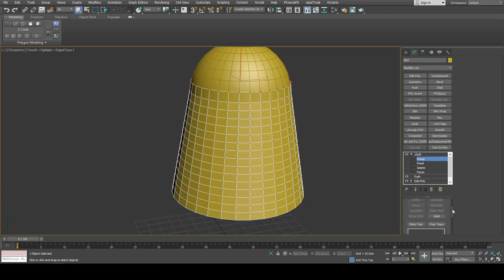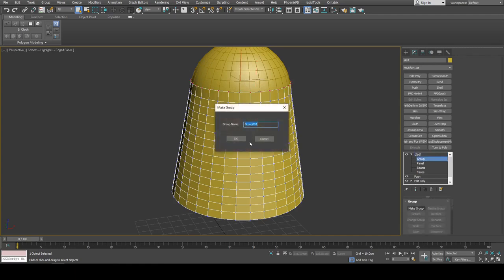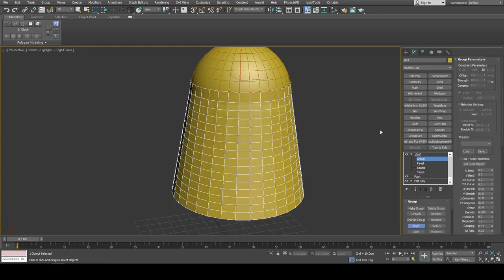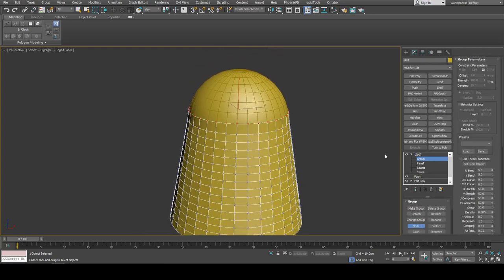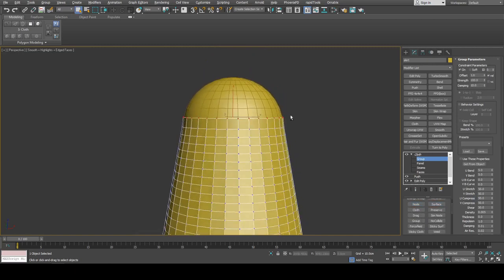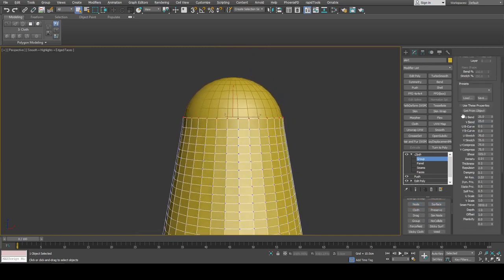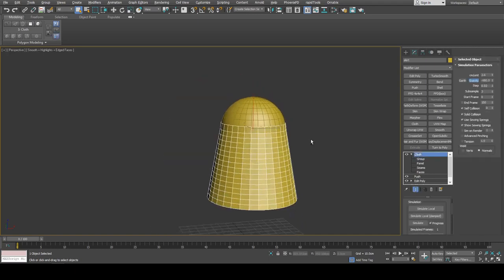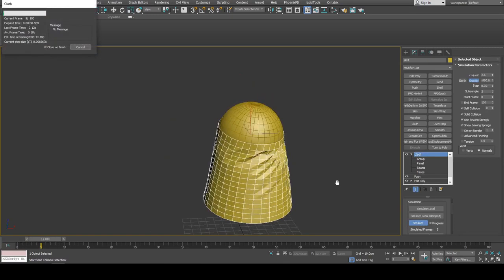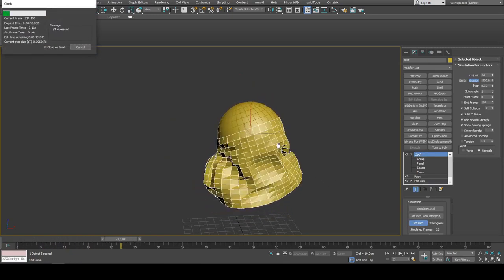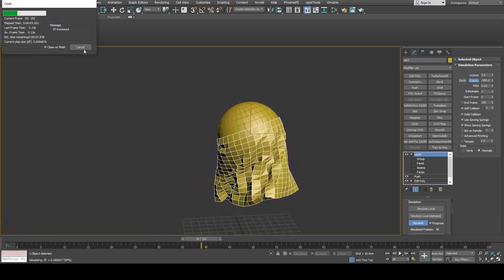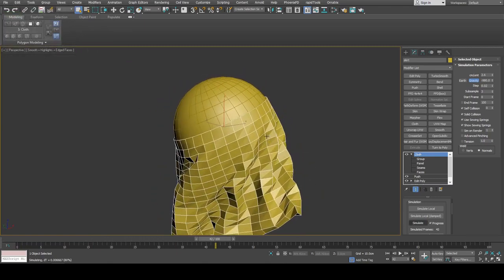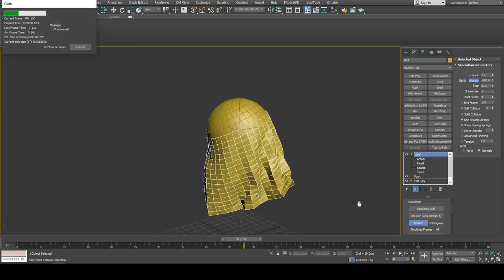Alright, and then we're going to scroll up here and then make group. Okay, click on node and click on the sphere. But notice how we can't really click on it. Choose surface instead. Alright. Get from object. You can use soft selection as well. Alright. So let's resimulate. As you notice now, those vertices are attached to the sphere, which we can say are hips, for example, and the simulation now works with no problem.